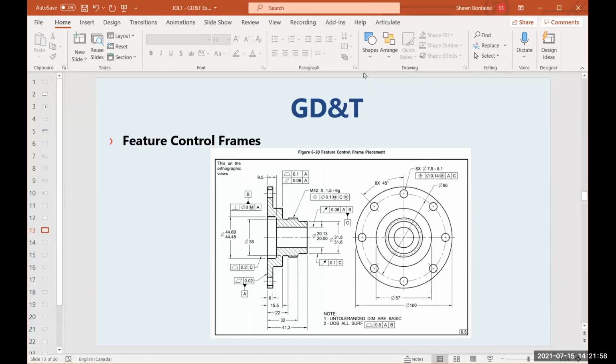Why do I not see A, B, and C datum planes? Usually they are supposed to be physically stated on the surface, correct? So I see the datum plane under this tolerance, the flatness 0.02, but physically it's supposed to be shown there, no?